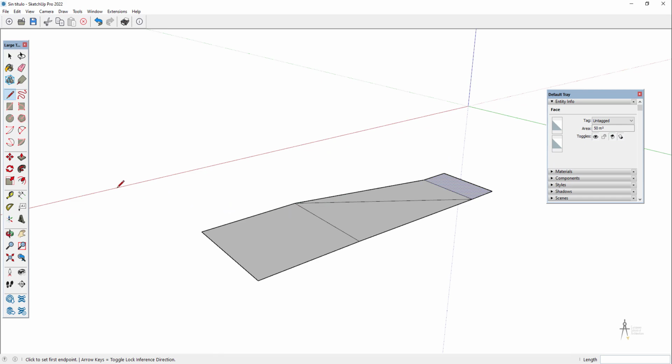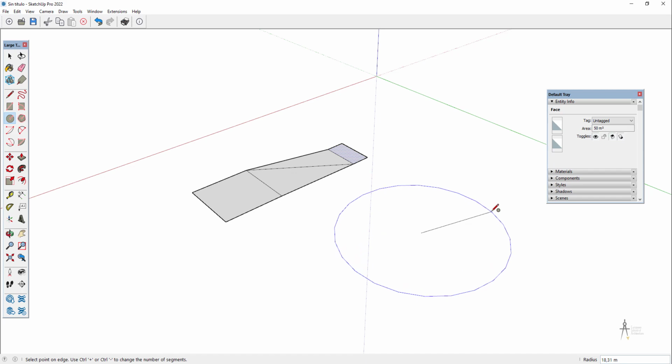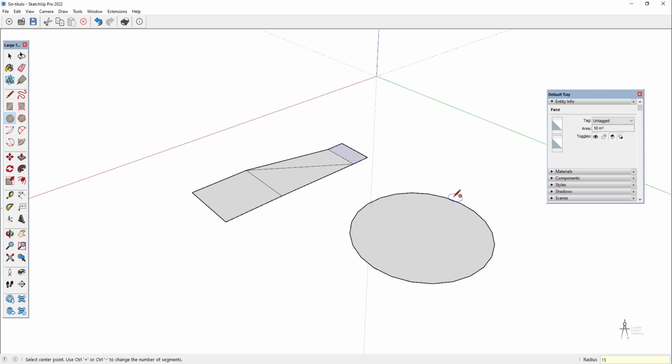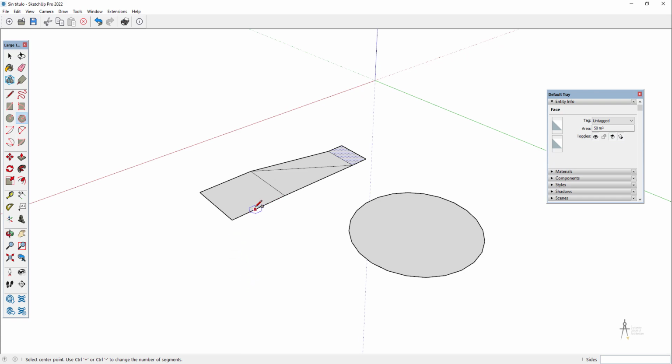Apart from drawing rectangles, I can do circles. Instead of the dimensions of the rectangle, I just type out the radius, let's say 15, and also polygons. So I can start wherever I want, any of these anchor points, or I can start, as I did, and also introduce the radius 6, for example, and there we go.